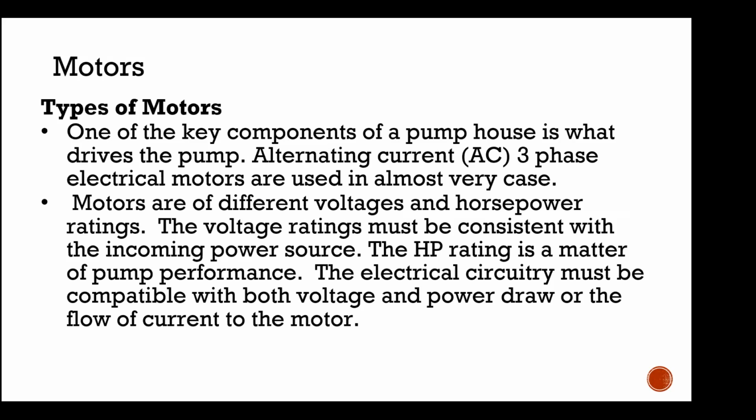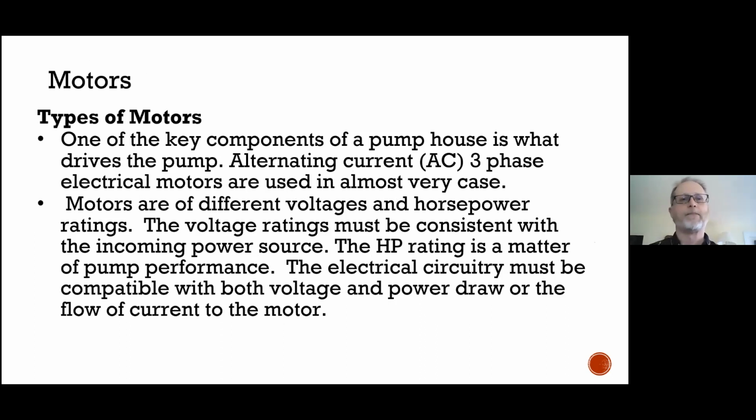When we're talking about a water distribution system, we're really talking about booster or inline pumps, or pumping to a reservoir from a treatment plant or to an elevated water tower. To do that, we need a motor, sometimes called a prime mover. We have to impart energy to the pump and then to the water column. Think back to the hydraulics we've talked about, where we're really talking about adding energy to create head, whether that's in meters or feet. We need a vertical column of water sufficiently high to push water to all of the areas of our distribution system, and hopefully for 24/7.